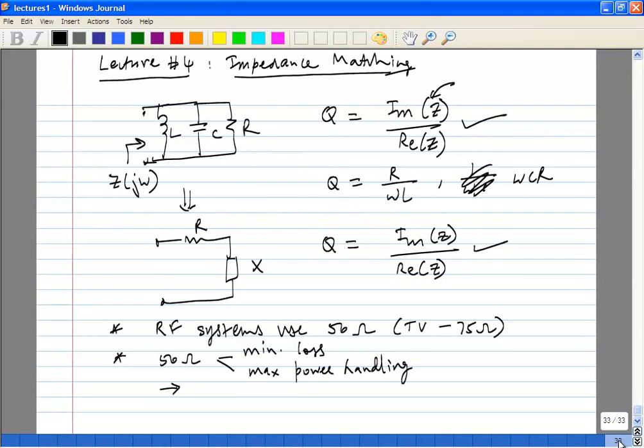So the thing is, remember that depending on the impedance, you'll have to have a certain swing, based on your power supplies and so on. In general, the lower the impedance, the higher the power handling capability, right? So for smaller voltages, you'll be able to transmit larger powers. So definitely that is one input into how you choose your standard impedance.